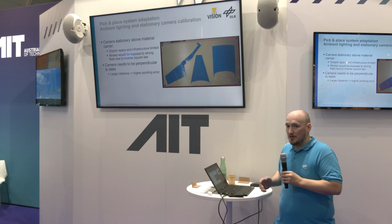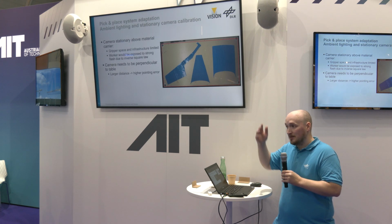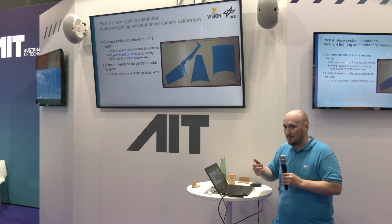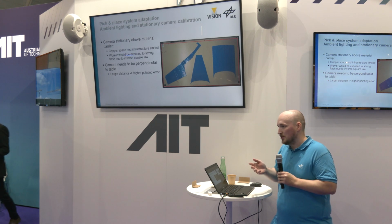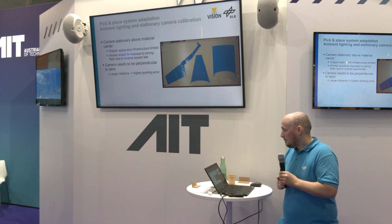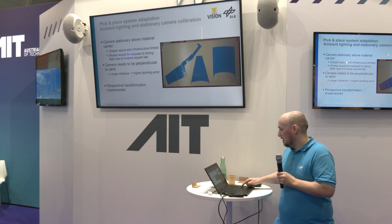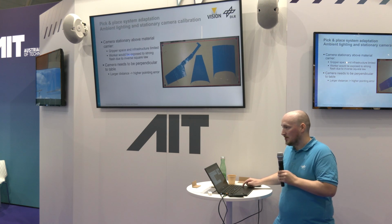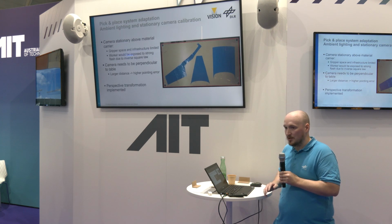And also then we need a perspective transformation, since we can't put the camera in this height directly perpendicular to the table. When using a robot, it's really easy. You can change the position of the robot to be directly perpendicular to the surface. So perspective transformation was done, and you can see in the image directly that these red squares are the same, and with the transformation the final image is quite well calibrated and rectified.